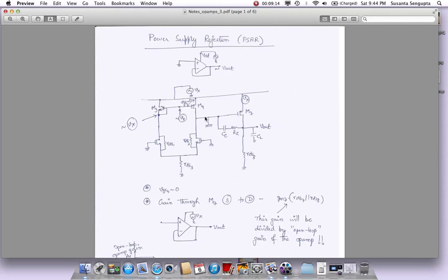The gate we were trying to find out, and we kind of came to a point intuitively which shows this is going to be a small value, and we don't need to worry about it being anything comparable to Vx, so we'll just assume it to be a small value, and that creates a current here, right? Low frequency wise, the current here is going to be GM times Vx roughly. Okay, it will create a current.